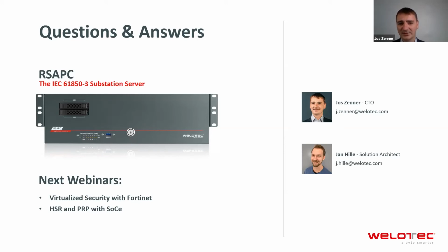Of course, if you're going to the Bay level, you need to have PTP timestamping, and there you need to add some kind of real-time hardware. We have a RSAPC card, which is optional for the equipment, which is allowing you to do the PTP timestamping. Hope that answers the question.